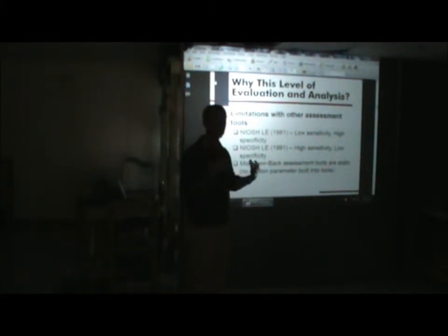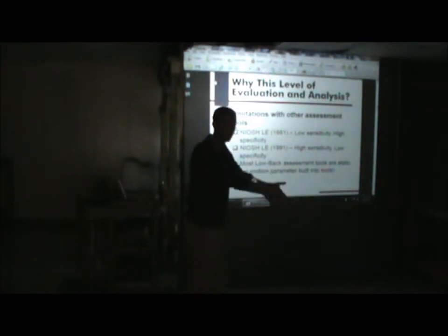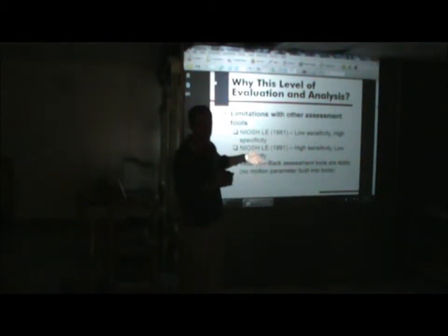This is a software that allows you to position a person into an assumed posture, apply the forces at the hands, both the magnitude and the direction of the force, and then it'll calculate moments about different joints. It compares those moments to strength capability values and tells you what percentage of your population is physically capable of performing that particular exertion. It also calculates static compressive forces on the spine at L5-S1, the bottommost disc in the spine, and one up from that, L4-L5. But it's a static model, right? So it does not include motion.